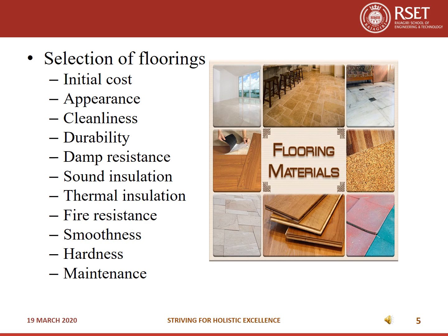When we are selecting a flooring material, we should consider the initial cost, that is the cost should be less, the appearance, cleanliness, durability, damp resistance, sound insulation, thermal insulation, fire resistance, smoothness of the floor, hardness of the floor, and the maintenance. The maintenance cost should be less for a good flooring material.